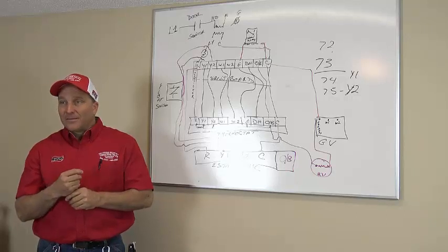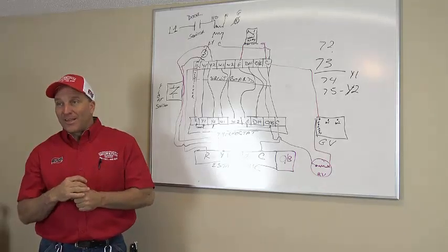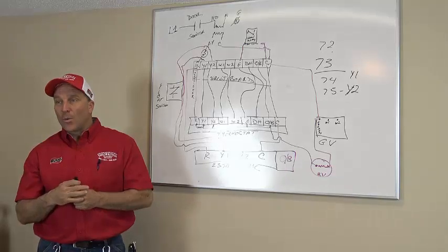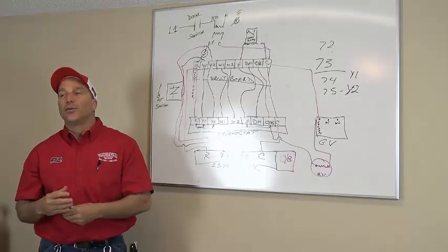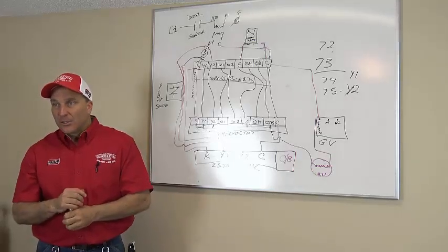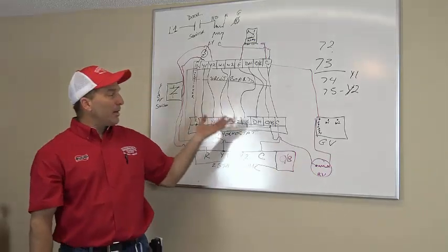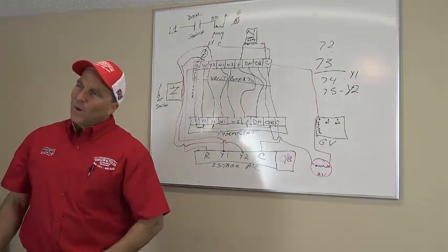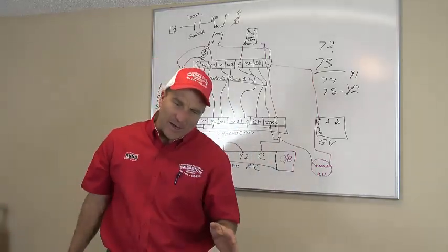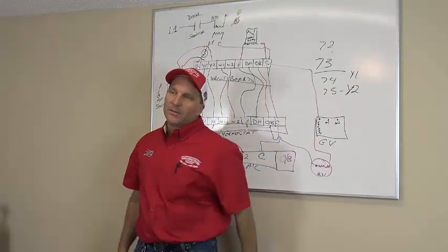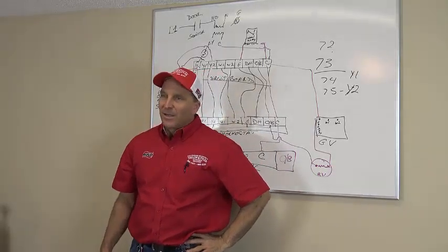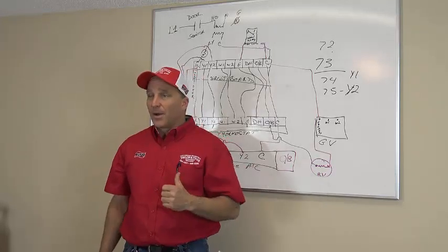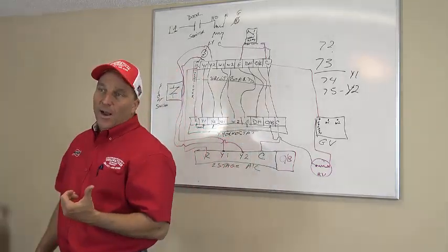Everybody got that? When you turn a heat pump on, it energizes O and Y1. Then O, and then Y2 second. So now my heat pump's running. Is W energized at this point in time? Well, wait a minute. Y'all said that W was for heat. Why am I not energizing W and I'm running heat? That don't make any sense, right? Because it's a heat pump. It pumps. That's why. The air conditioner.